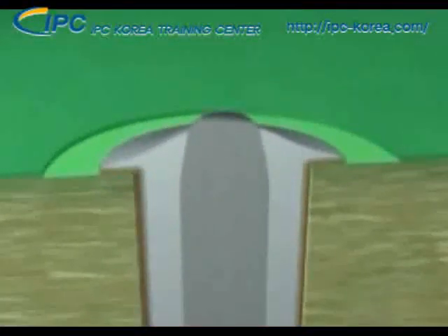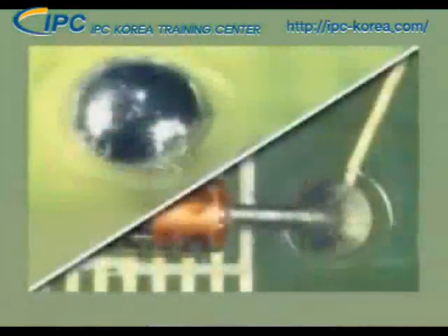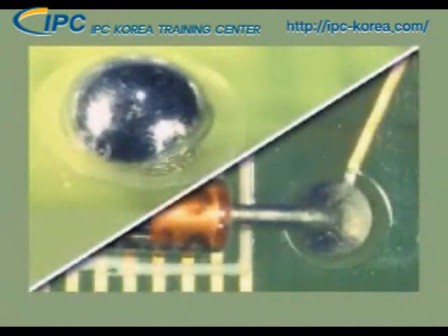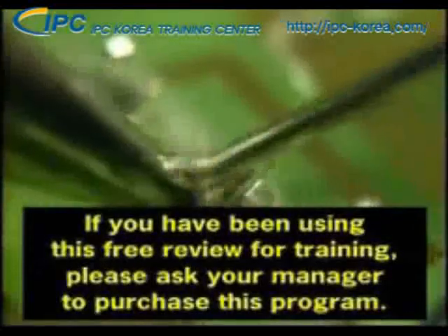The minimum requirement occurs when the fillet is slightly convex with good wetting and the lead is not visible due to excess solder. You need to make sure you can see the lead in the barrel from the component side of the connection. This condition is called a process indicator, meaning the cause of the condition should be corrected in the soldering process.